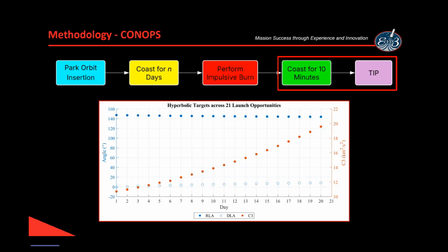Yeah, so that kind of gets into this question just now, where delta V is a great general way to look at things without having to get vehicle dependent. So that's why we chose to go delta V, but the other parameters you would consider would be things like payload weight or propellant weight, that sort of thing. But then you have to know what your stage weights are, the ISP of the fuel, for example.